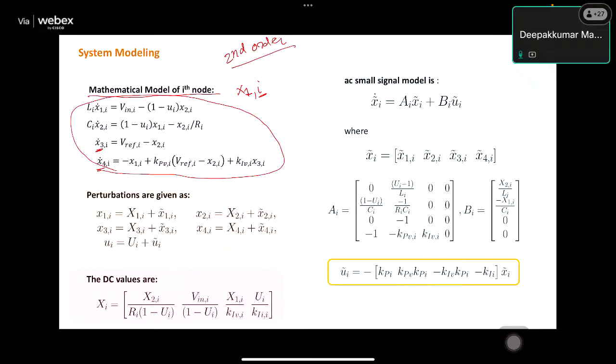See, what we want to do here, our objective is to actually calculate that control. Therefore the controller is designed by using the classical method, the dual loop PI controller, but the observer I will design by using this state space based method. Therefore we are converting from time domain to frequency domain and again to time domain. So these are the equations. These additional states x3 and x4 are contributed because of these two integral actions which we are adding.